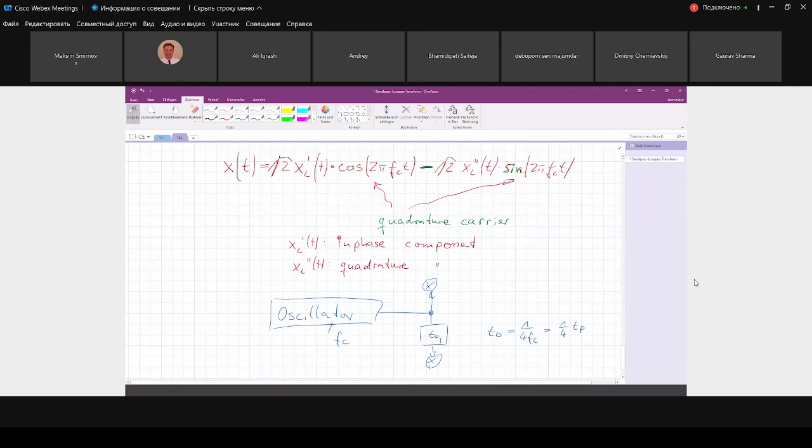Since the carrier frequency and the bandwidth of the signals are so low, you can realize this time shift very precisely, because everything is digital. Even the multiplications are realized in the digital domain, so everything is absolutely precise. Then you basically have an upconversion in the digital domain, on sampled signals, to a center frequency of, let's say, 100 or 200 megahertz. It depends on your bandwidth.